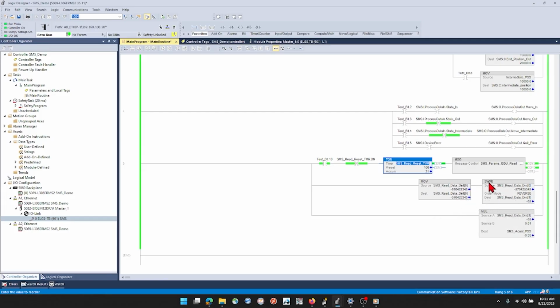And then we have a swap byte instruction through Rockwell here. Basically what we're doing is taking the DINT, the double integer value, and swapping the order that we're reading. Instead of reading it from bit 0 through bit 31, we're reading it bit 31 through 0. We're swapping that byte order, and that gives us this value here, from this value to this value.